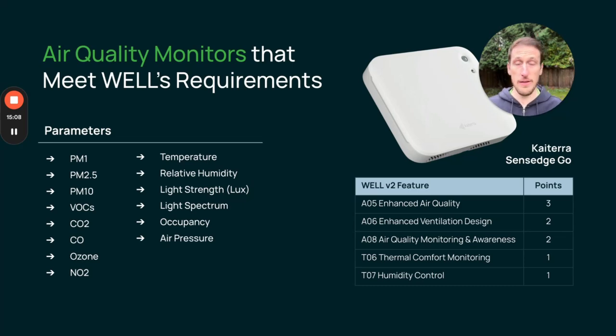I guess another con on that front is that you actually need to spend a little bit of time upfront to really identify the technology that you want to work with, look through the spec sheets, compare it to the performance verification guidebook on WELL, and make sure that each of those lines match up, right? So that your monitor is compliant and it is going to do all of the things that you think and you want it to do. Because it is absolutely true that not all monitors will do this right off the bat.